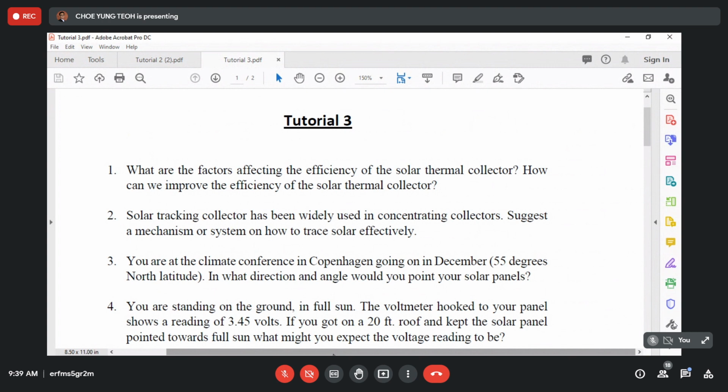And the function of the cover, of course, is to avoid the heat loss due to convection. So you do not want to have any blockage by the cover. Okay, so the cover is a good thing for most cases, but for locations which have a low convection rate, then the cover is not a necessary item.